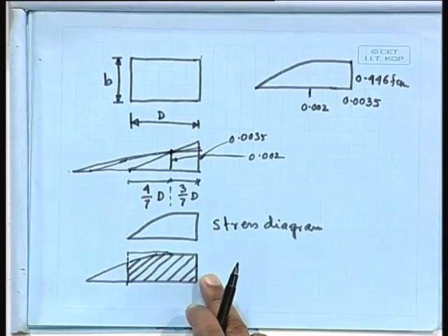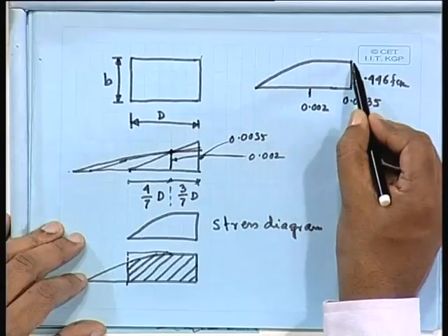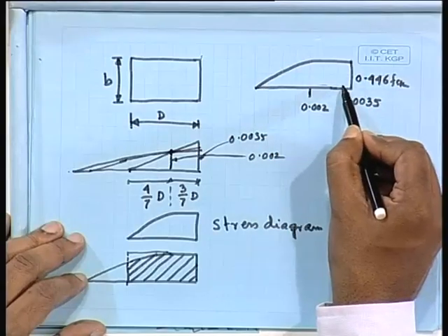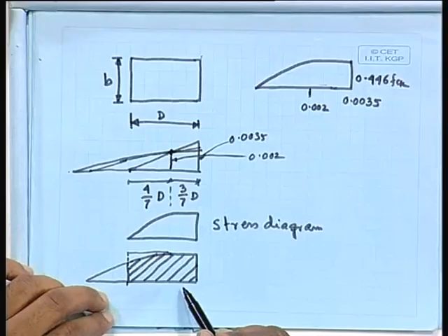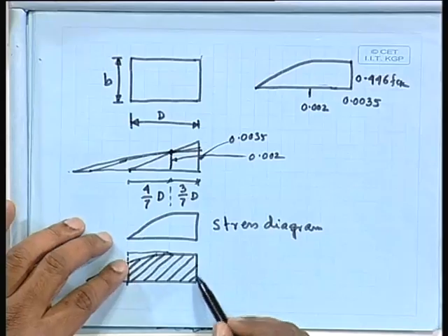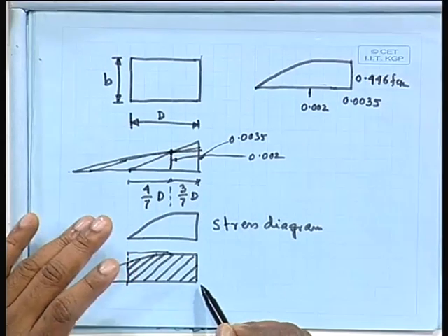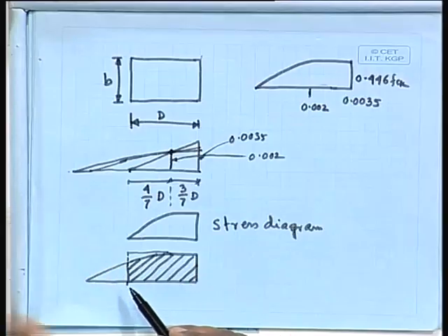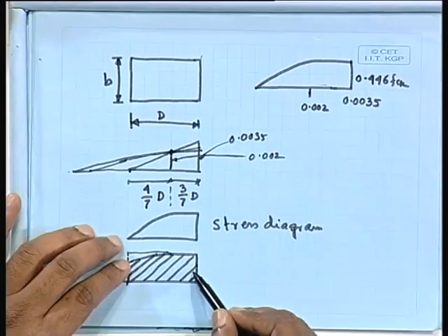Compared to your beam problem, there is no problem because we are taking the whole area, but whenever you are talking column, in most of the cases, it will happen that it is partially loaded, that is the stress block will not get the full one, we shall get part because neutral axis is outside the section, and this area we have to calculate.